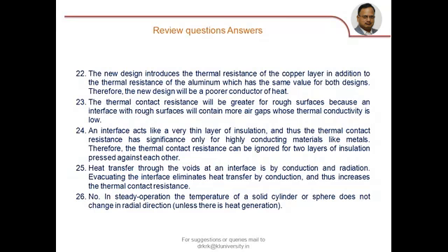And heat transfer through the voids at the interface is by conduction and radiation. So by evacuating the air and doing it under vacuum condition, the thermal contact resistance will decrease. In steady state operation, the temperature of a solid cylinder or sphere does not change in the radial direction unless there is heat generation. Hence, the answer is no for it.